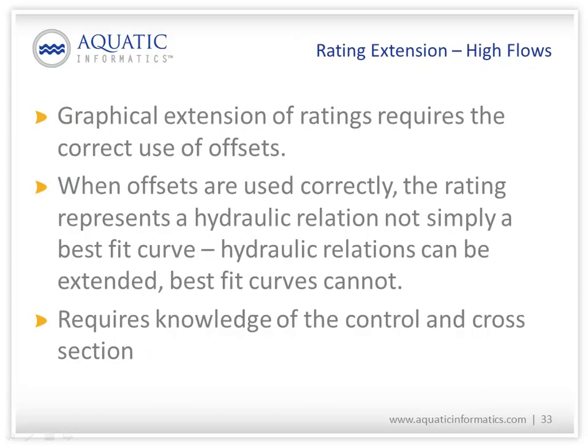The use of the curve extension tool in AQUARIUS really works quite well because we've taken some care to make sure that we've correctly identified our offset values. When offsets are used correctly, we're talking about a hydraulic relation, and it's quite reasonable to extend a hydraulic relation as long as we understand something about the control conditions and the cross-section configuration. This is different from just fitting a curve by eye through a scatter of points or using a statistical method, where your confidence in extending a curve would be much, much lower.